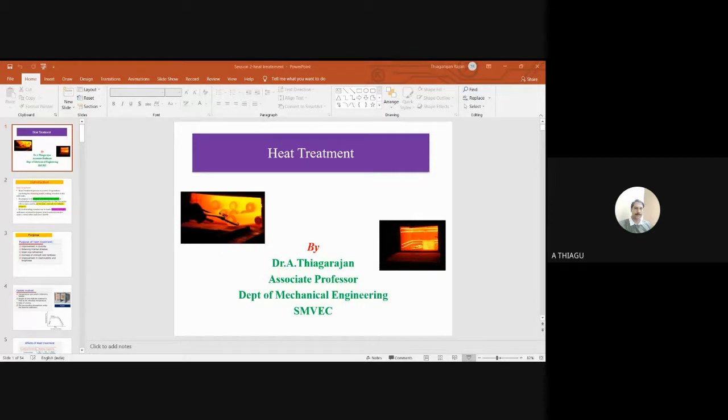So the next concept I want to touch is the case hardening process, or surface hardening process. Here the outer surface is coated with carbon and nitrogen in order to increase the mechanical properties. We go for this process especially for gears, camshafts, universal joints, valve materials, couplings, flanges, bolts and nuts. Engine cylinders, pistons, wherever we have high temperature applications, we definitely have to do the surface hardening process.